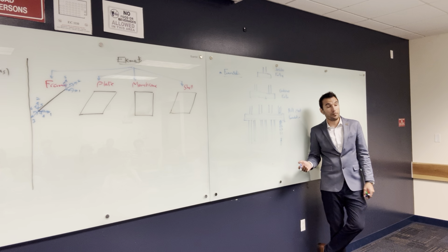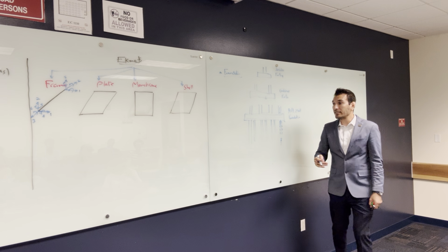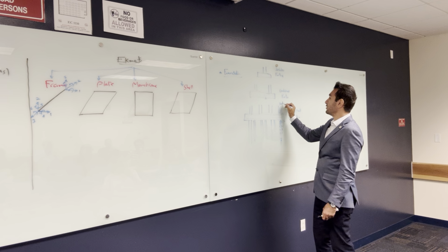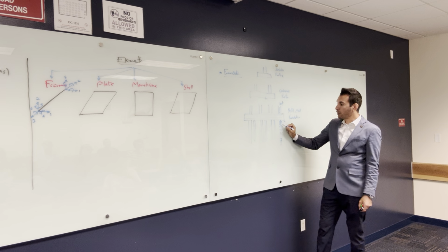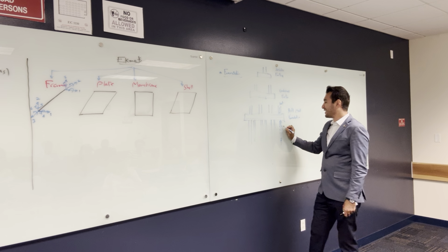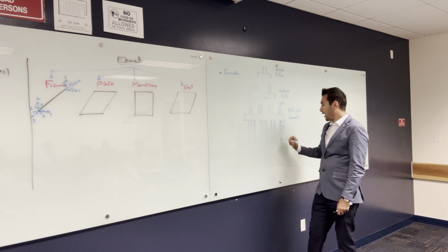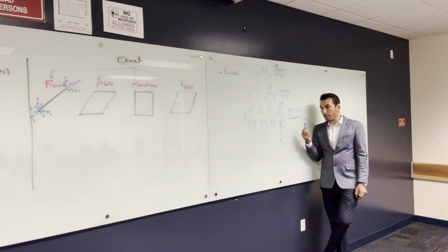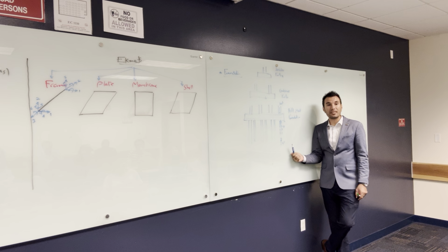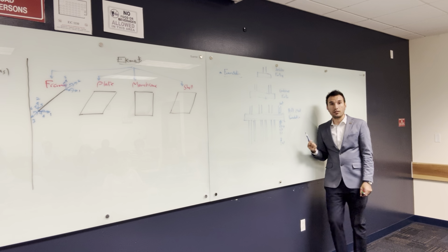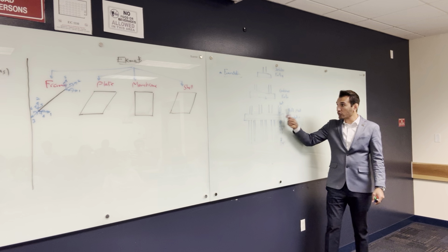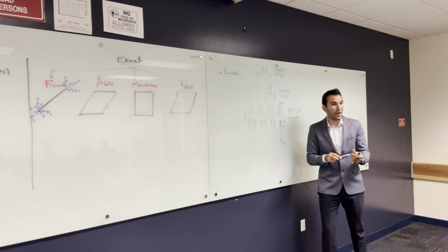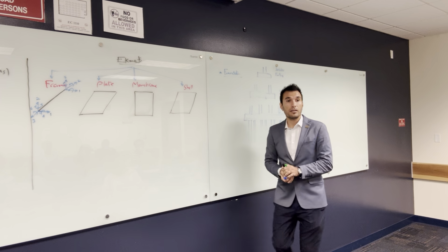So that's how we design piles. Basically, if I have 100 ton and the friction of one pile, let's say, can take 5 ton and the tip can take 5 ton reaction, so one pile can only resist 10 ton. So how many piles do I need to resist the 100 ton? 10. So I need 10 piles to resist this one. Okay, so that's how we calculate the number of piles that we need.